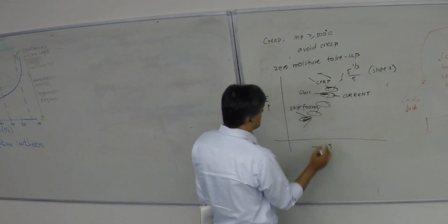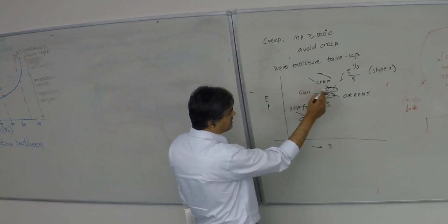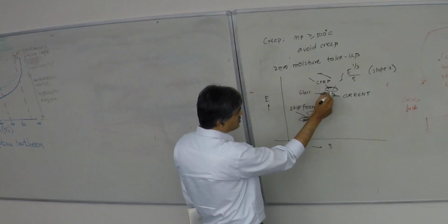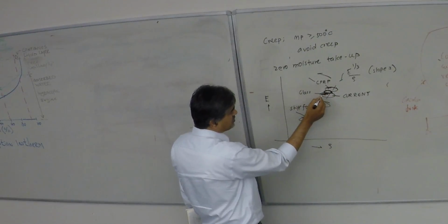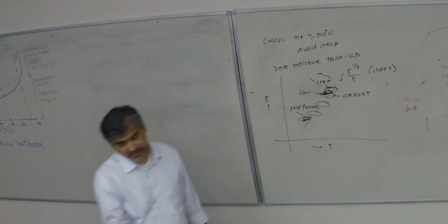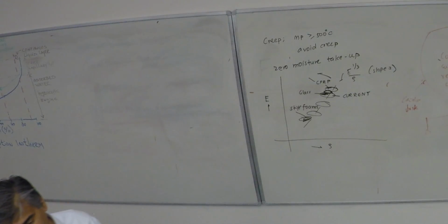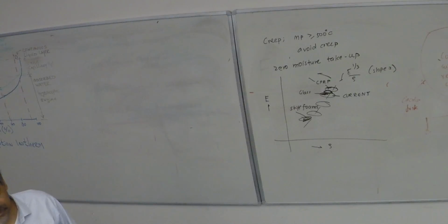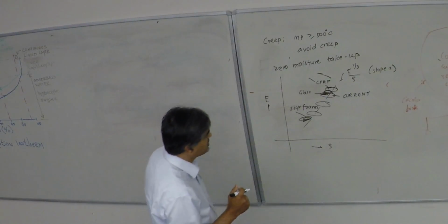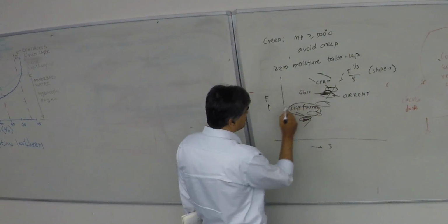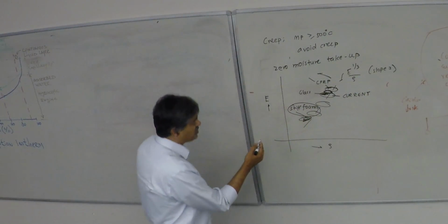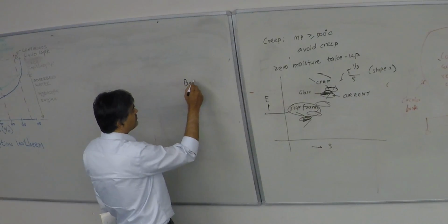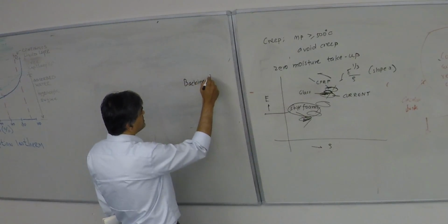You can get higher modulus at slightly higher density. Actually, this may be just overlapping this, because here we are talking about 2300. CFRP can range between 1.5 to 2.1, depending on how much percent of polymer or what grade of polymer you use in it. But certainly these are much, much lighter, which also suggests that the backing of these mirrors could be made out of very stiff foams.